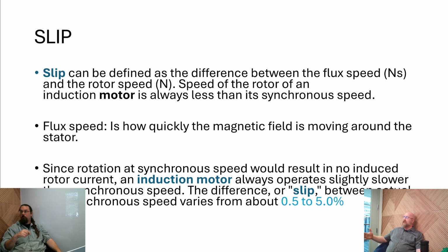And you've seen this at home. You turn a vacuum on and the lights dim. That's what's happening: you're drawing a lot of current as you start up that motor. Likewise, if your refrigerator compressor starts going, or your AC turns on, you frequently see your lights dim. That's because the motor has not gotten up to speed, and so it draws an enormous amount of current for a very brief period of time.